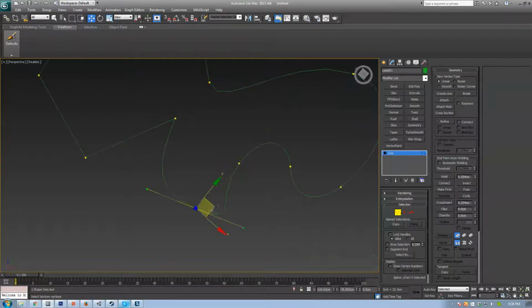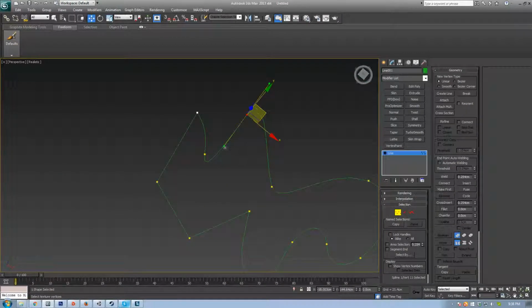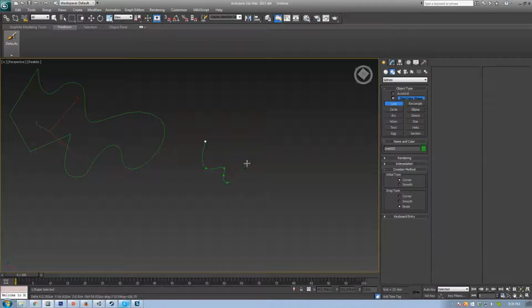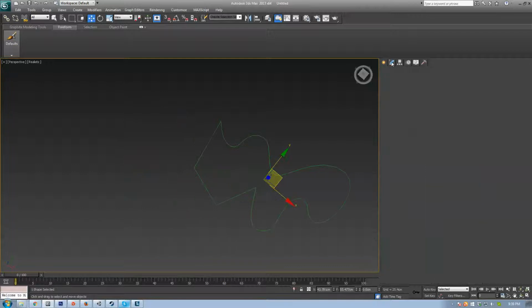So let's play around. Let's say I wanted to get some nice round shapes here, whatever it is I'm making. And typically the rule with any sort of spline work is, do as few points as you can, right? Don't add too many. If you started off and you're like, oh, I'm gonna add all the little detail to make all my edges, then you're just gonna have more points to adjust, and it's just gonna start looking all lumpy. So don't do that. Use few points.